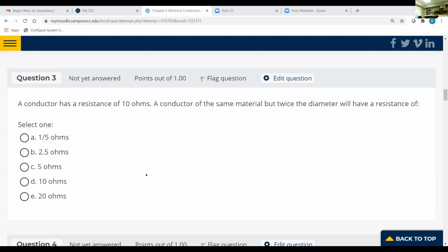Okay. Now, when you're measuring wire, you would express it in thousandths. You can put a 0 on there, and 10 thousandths is the same thing as 1/100. So these two here equal. Okay. Now, when you look at 10 thousandths, that would actually equal 10 mils. When you look at a mil foot of wire, 1 mil foot of wire.